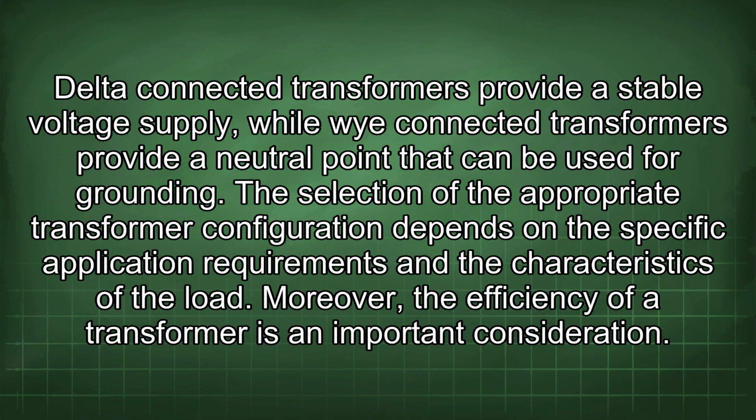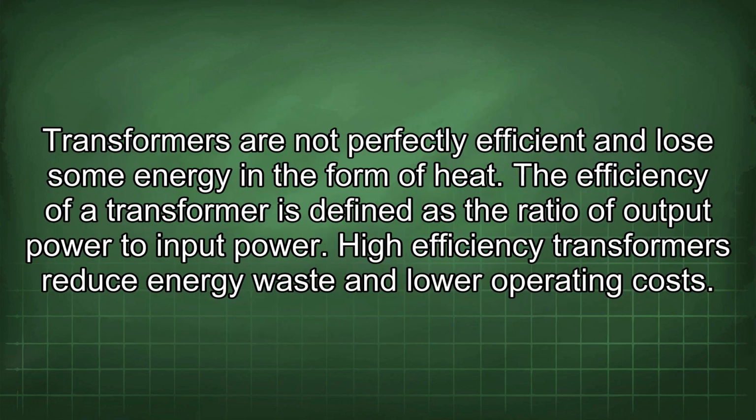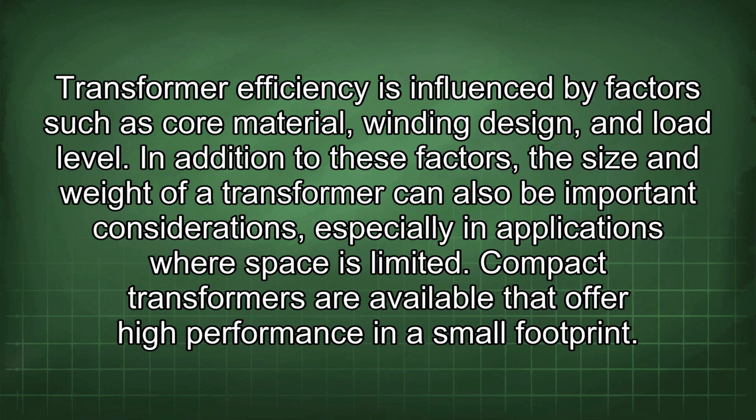Moreover, the efficiency of a transformer is an important consideration. Transformers are not perfectly efficient and lose some energy in the form of heat. The efficiency of a transformer is defined as the ratio of output power to input power. High-efficiency transformers reduce energy waste and lower operating costs. Transformer efficiency is influenced by factors such as core material, winding design, and load level.